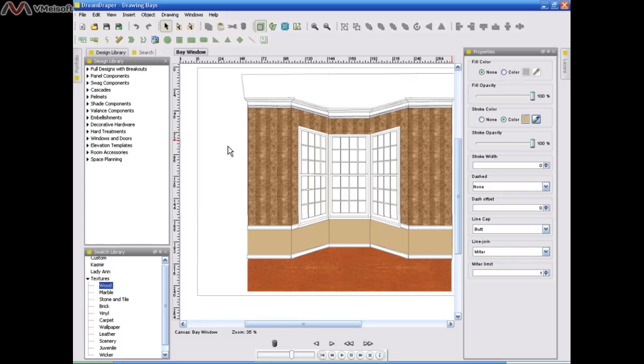I want to point something out with the polygon tool that we just used. I'm going to click on that icon once again, and I'm just going to draw a random shape like this. And if I double click right here, notice that the shape filled in completely. It closed. The path got closed. And this may be a little bit hard to see, but the line was created in the last color that we used. The last color that we used when we filled in our other polygon shape was beige. So when I created the line here for my polygon, it was also done in beige.